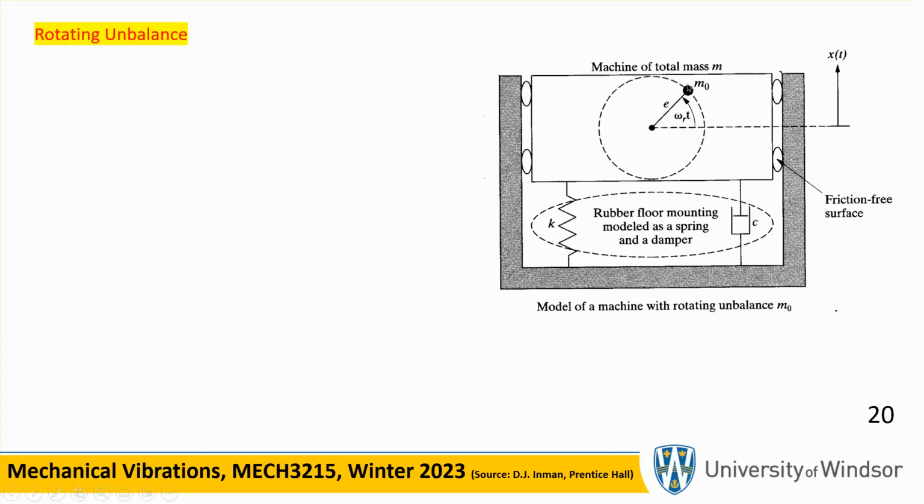Now notice that the imbalance mass, I call it M naught, okay? And the distance to the rotation center is going to be called eccentricity. And this is turning. Now, I know it's kind of confusing. What the heck? What do you mean by M naught? So let's think about it like that. Suppose, just hypothetically, this is a propeller, the blades of a fan.